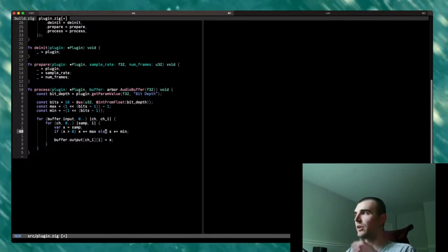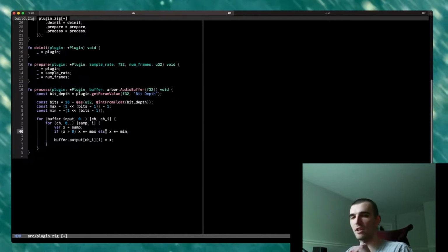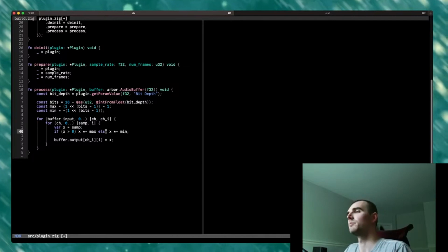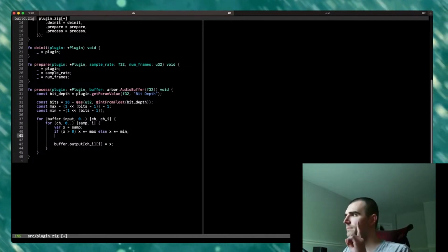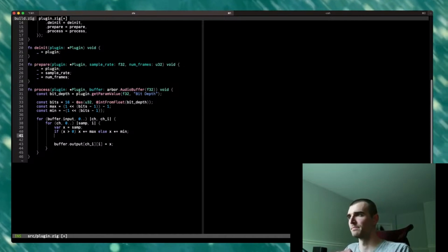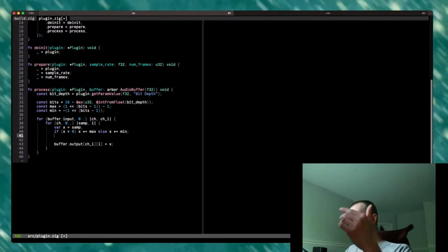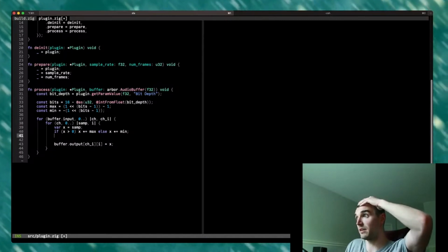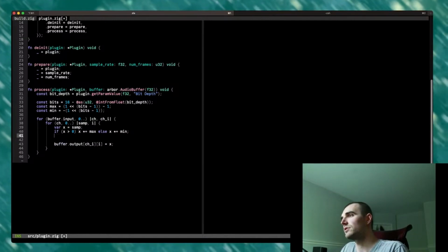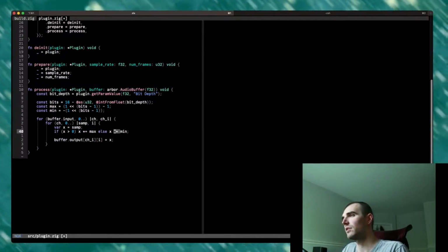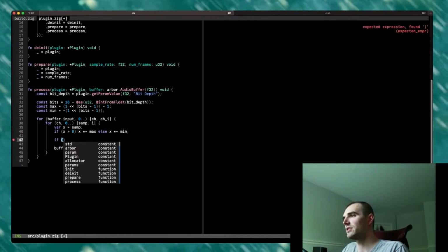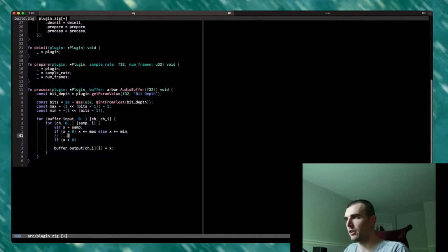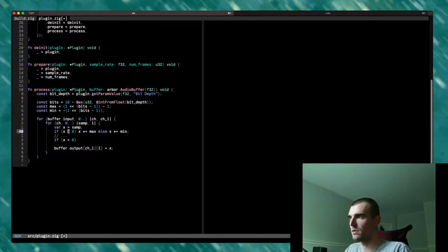And if we load it into the wave shaper graph in Plugin Doctor, we'll be able to visualize what's happening. But first, before we do that, we have to actually convert back to floating point. So we remap onto the integer range, and then we basically just have to divide by it again, right? So that'll be a separate check, because you presume that there's going to be audio processing happening here, crazy fixed point stuff.